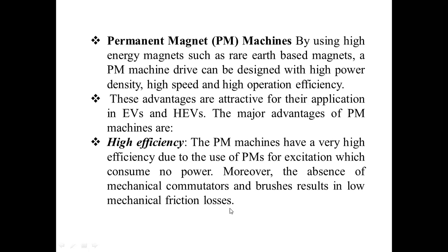So that's why the efficiency value increases, while reducing the frictional losses, iron losses, and also somewhat the field copper losses. While all these losses are reducing, automatically the efficiency of the machine drive can be increased.